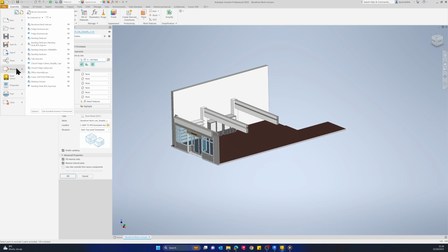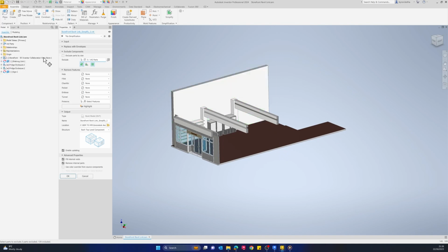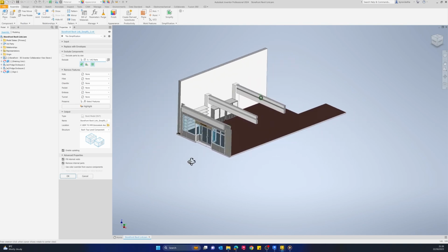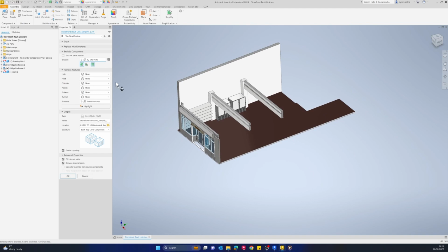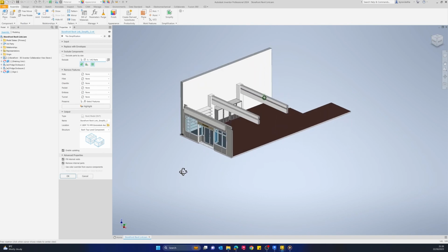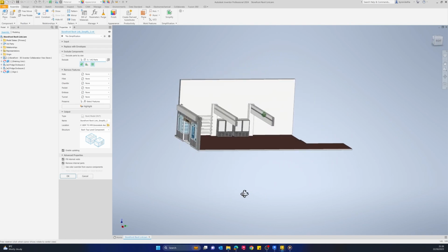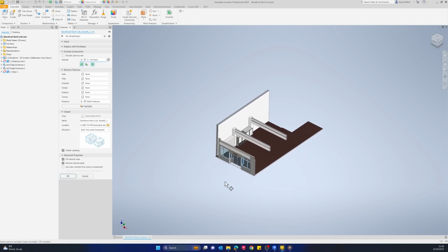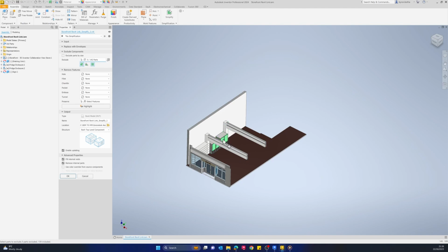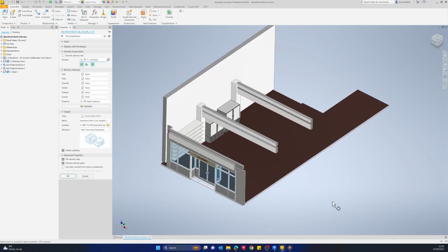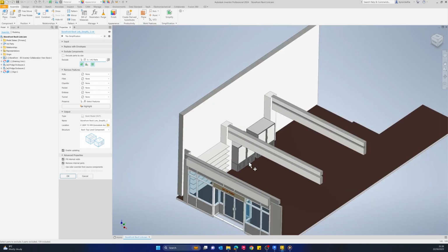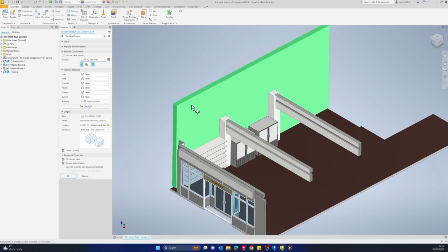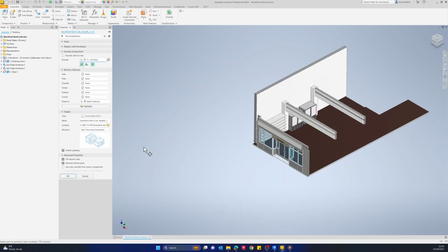So you'll see when I click that export to Revit, the simplify dialog box pops up and the output type has automatically been set as Revit for us. We do have an in-depth blog if you wanted to have a look at the simplify tool set. It's really useful for exporting individual units out and simplifying them so that you're not taking all of that Inventor data that Revit may not necessarily need out. So it's making compact models of your intricate designs that you use for fabrication, and then other people can use them inside Revit to populate their models.